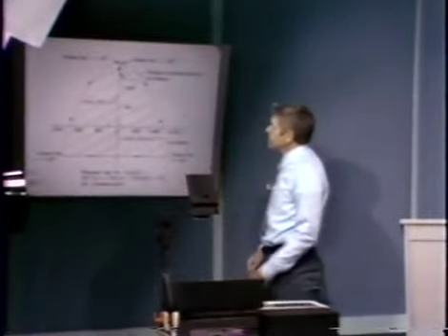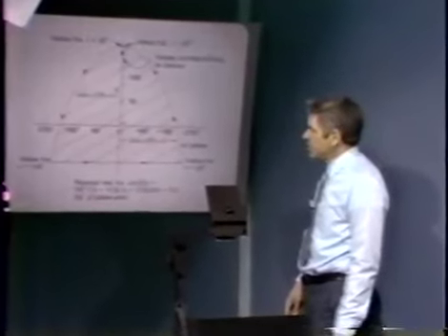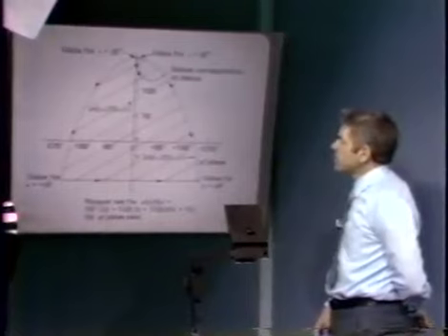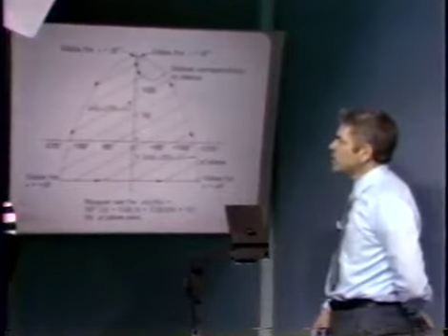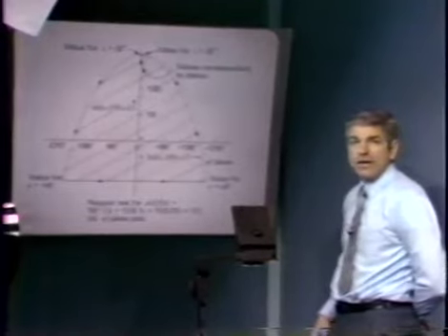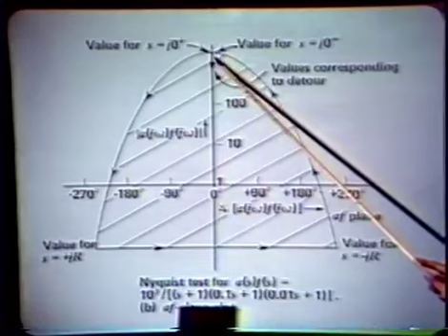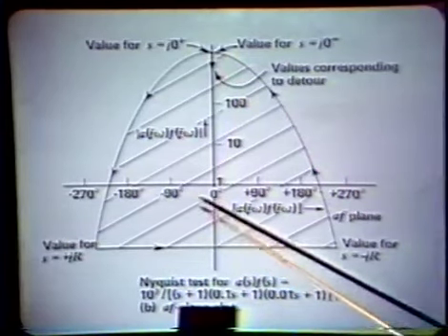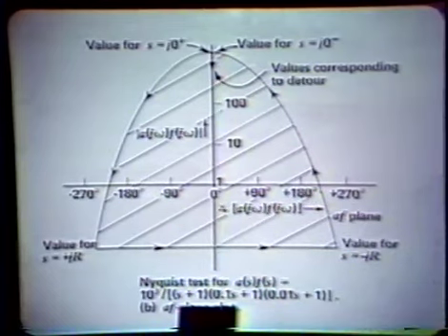This apparently is an A0, F0 product that's large enough. For this particular location of the three real axis poles, the particular relative location, we find out that an A0, F0 product of 1,000 is enough. We can convince ourselves of that, for example, via a Routh kind of development. But that's shown in the Nyquist construction in that we have two -1s of the AF product that result in four values of S with positive real parts.